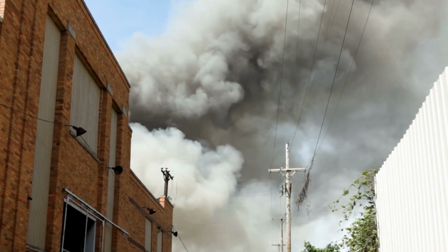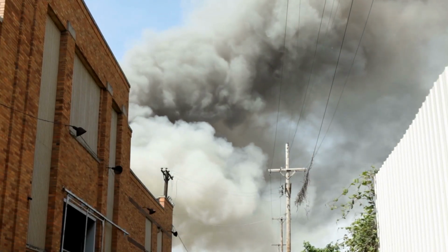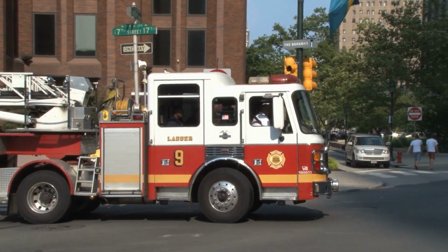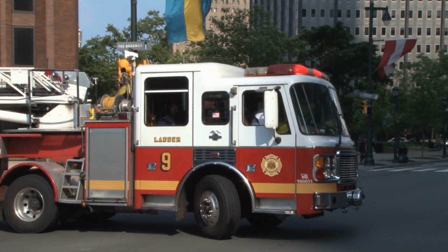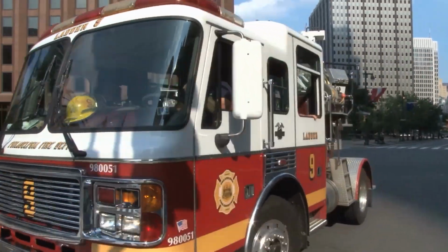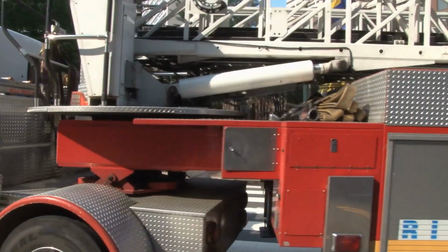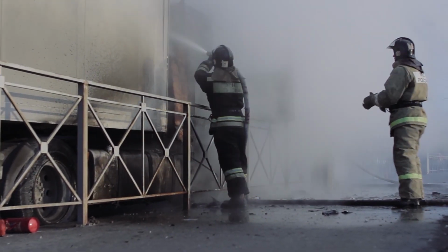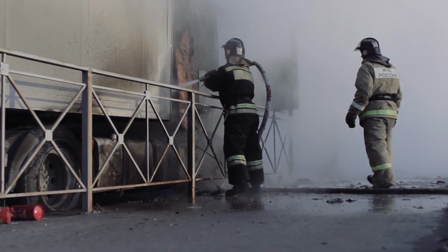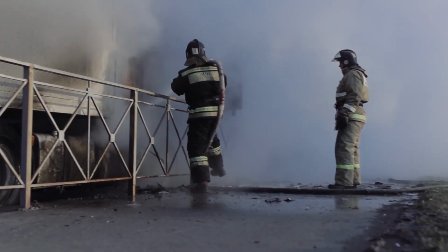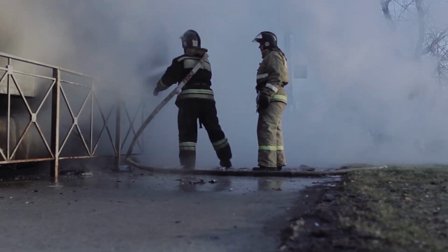If you are performing hot work where fumes and high heat will be produced, be sure to communicate with the proper personnel. This may include facility employees or even the local fire department. This is especially important for sprinkled locations, since water from unintentionally activated fire suppression systems can incur huge financial repair costs, not to mention the dangers the sudden introduction of water in your workspace might produce.